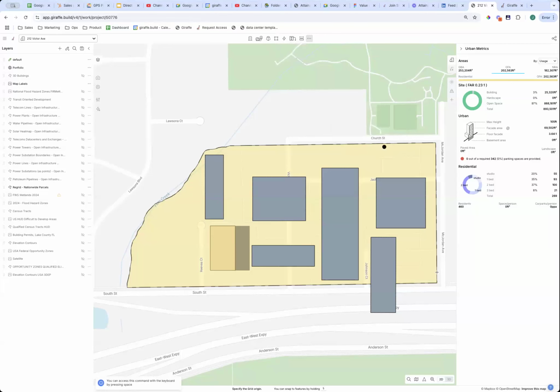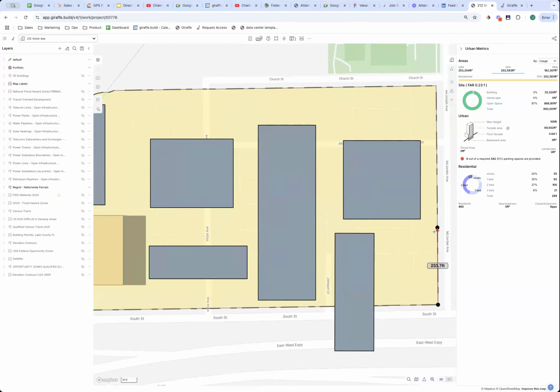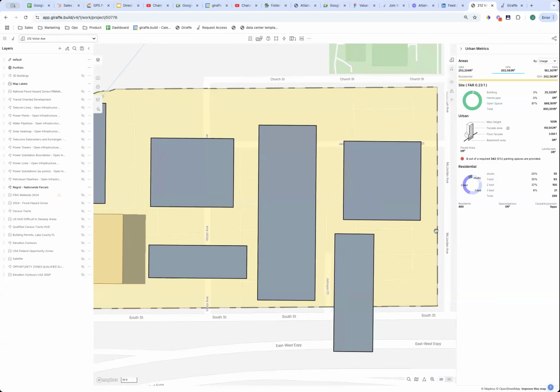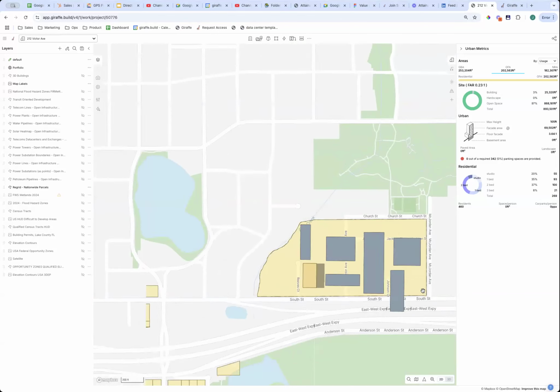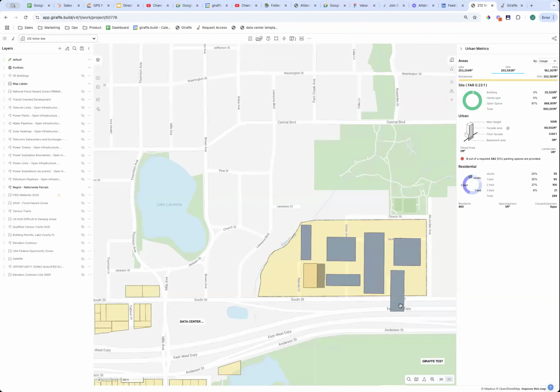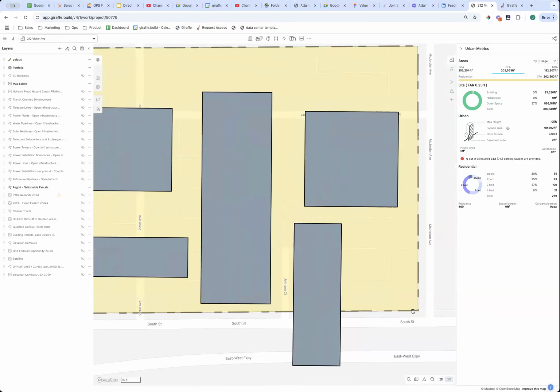I want to edit the grid, and I'm going to select the corner of the site here and go up the boundary. I'm just holding S to snap, and I don't know if you noticed that, but it just tweaked the screen by 1 degree basically. And now my project is going straight up and down to the site boundary, which is super helpful.